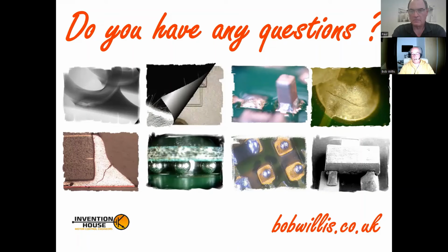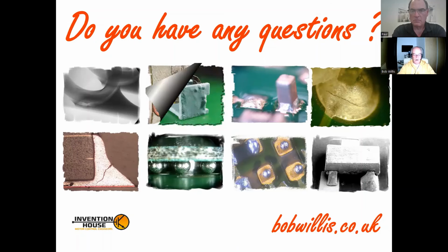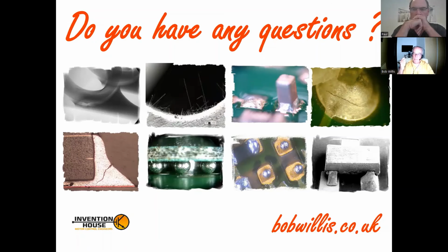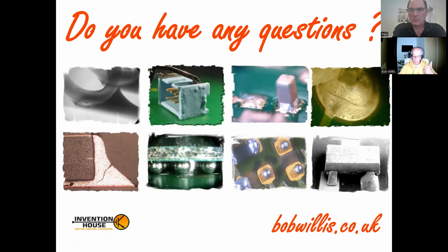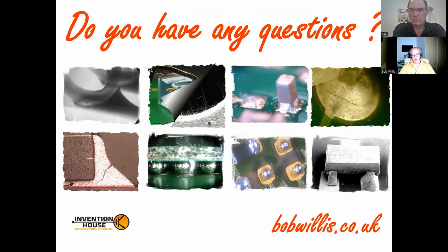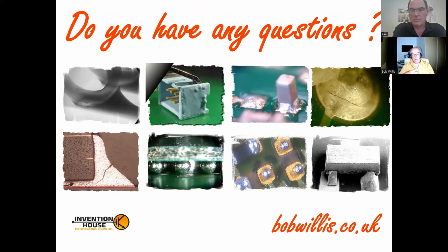It's interesting you say that. I used two different coating methods in my youth when I very first started in electronics. One was parylene, the Rolls-Royce of conformal coating, and one was acrylic with a paintbrush. So the most expensive and the cheapest. I never experienced personally a problem with any of our products, and they went into space applications and military applications, with parylene. Parylene is nice. It's expensive, but it's nice because you get the thickness you dialed up if you want, it can be compatible with no clean, though it's very rare for people to use it with no clean, and it's guaranteed to give you the coverage where everything's exposed.